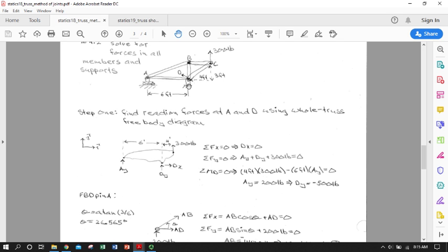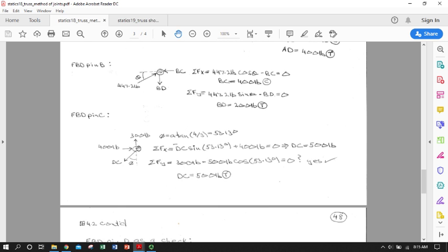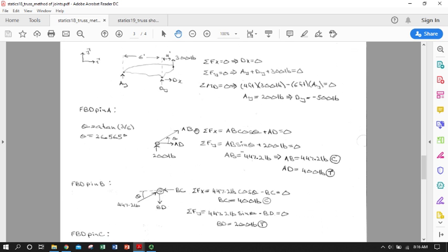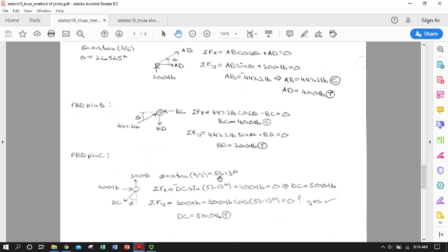So that only leaves two more joints that we could look at. We only need the force in member DC, so we're definitely going to have a check equation. So if I take pin C as my next point, I pick up the 300 pounds applied external load. I have 400 pounds being applied in the positive x direction coming from my force from BC, which is in compression. So if the pins are, again, applying compressive force to the member, the member pushes back on the pin. So that gives me insight into direction. And then I have the force due to member DC coming out at an angle phi, which I have to go back to my schematic to get. So I have 4 feet in this direction and 3 feet. So the way I've drawn the angle phi, it should be arctan of 4/3, which should give me 53 degrees.